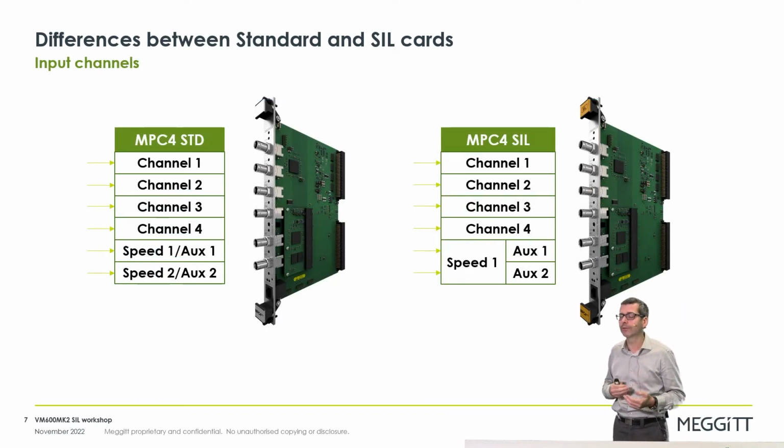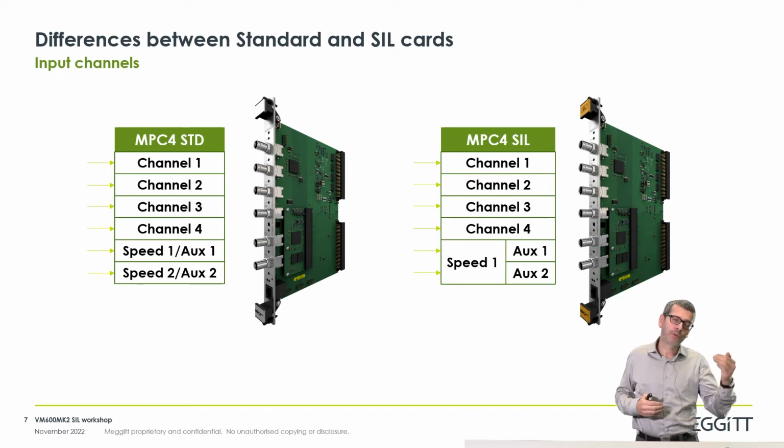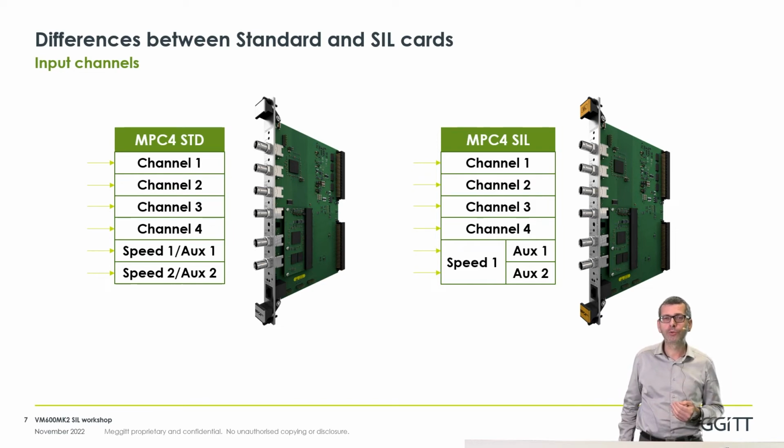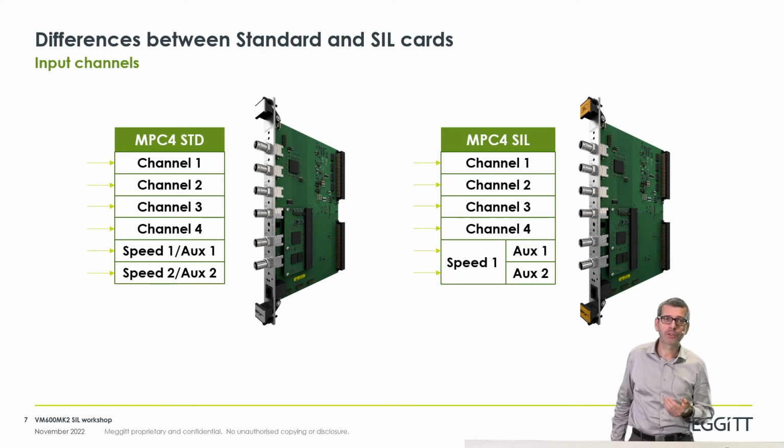In terms of card capabilities, if we talk about input channels, both standard and SIL have 4 dynamic input channels and 2 quasi-static input channels. But there is a difference regarding the speed channels. On the standard card, we can connect 2 speed sensors. On the SIL version, only one speed sensor is supported.